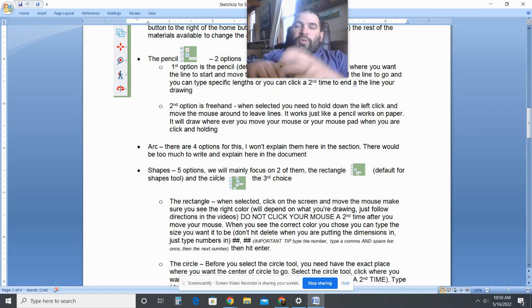When we're going through the videos, I typically will tell you, and I should have that pre-planned. So you just have to type in the 2 different measurements, separated between each other with a comma. For instance, on the first assignment, we're going to make windows on 3 of the 4 sides that we create, and we need to put the width first. So we're going to put 48, comma, space, 36. That would make a window that's 48 inches wide and 36 inches tall.